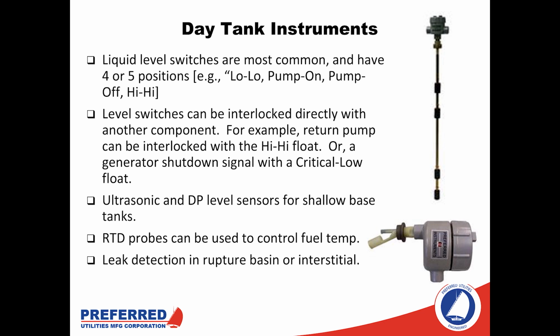For the bulk storage tank, we're not trying to so much control the level beyond just preventing an overfill. We're merely trying to inventory, so we would use an analog sensor. For the day tank, we're not just trying to determine how many gallons are in there. We are trying to specifically control the amount of fuel in there.